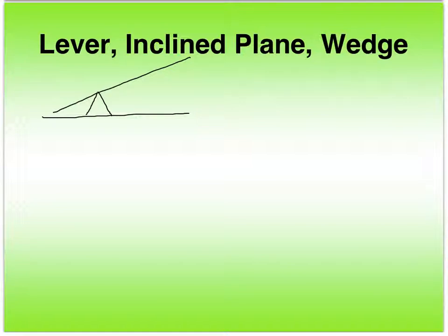But when we deal with it, we mostly deal with the vertical displacement of both sides. Now, when this lever has been moved up or down, let's say the blue is the new lever. If I was to move it downward and upward here, this will actually create a distance here in red and a distance here in red, and you'll have to use different forces on either side. This longer distance over on this side will require less force than this shorter distance on this side.